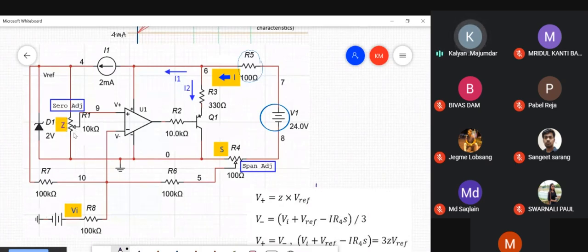If the wiper is at the lowermost point, then Z is 0. If the wiper is at the uppermost point, Z is 1. So Z is a fraction which varies from 0 to 1 depending upon the setting of this wiper. So a fraction of the reference voltage becomes the input to the non-inverting terminal of this op amp. So the first line says that the voltage at the non-inverting terminal is some fraction Z. This fraction Z is determined by the setting of the potentiometer, and the setting of the potentiometer is manually determined. That also acts as a zero adjustment. How? We'll come to that.